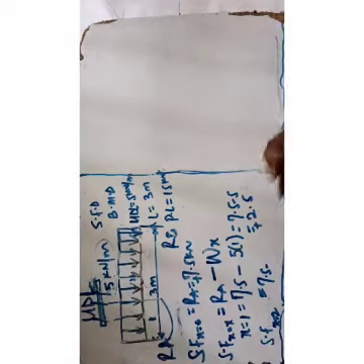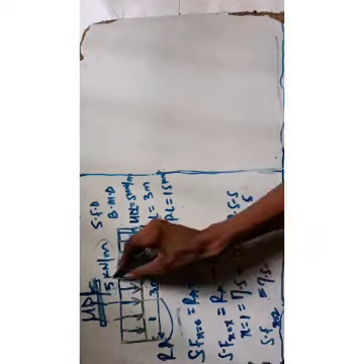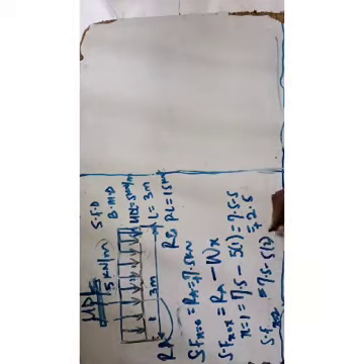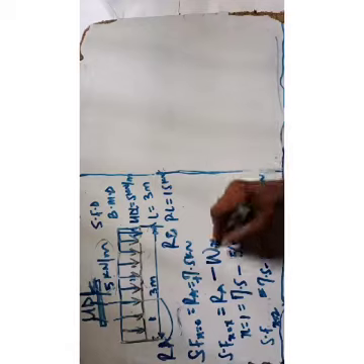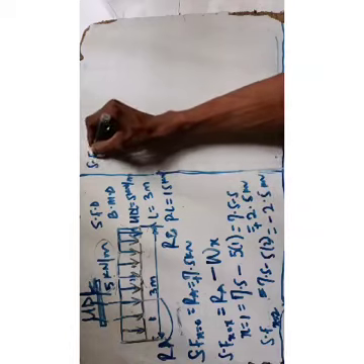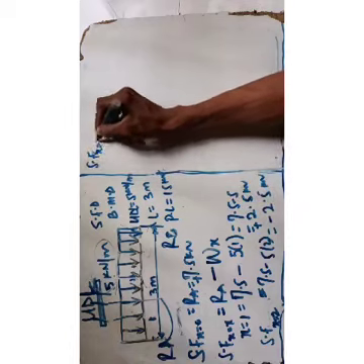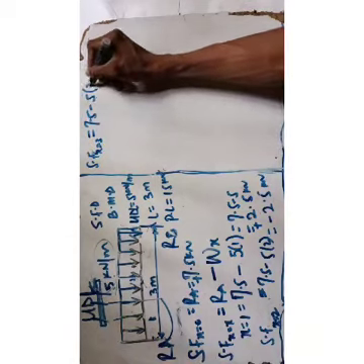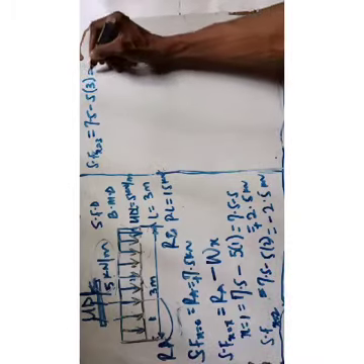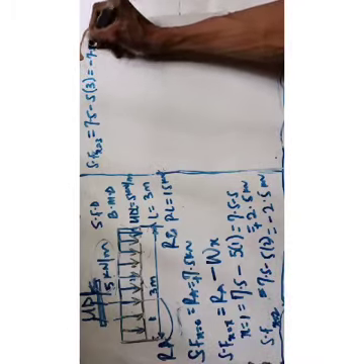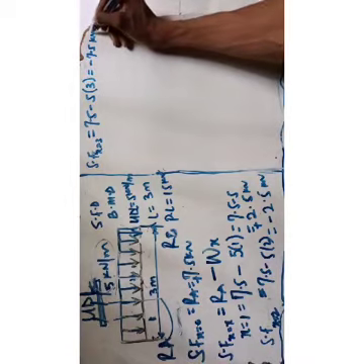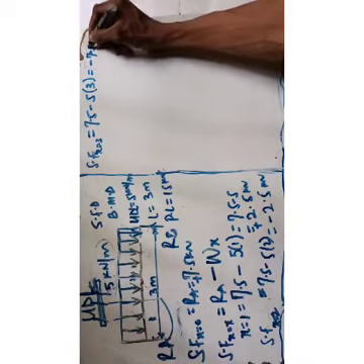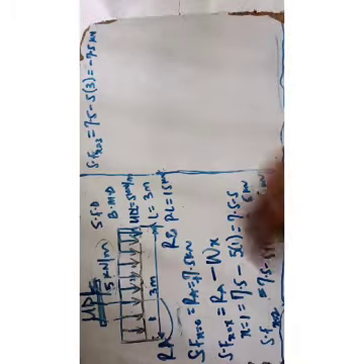So you're going to have it as 7.5 for x equals 2, 7.5 minus 5 times 2, and that will be equal to 7.5 minus 10, okay? That will be minus 2.5 kilonewton. These are all kilonewton. Then the shear force when x equal to 3, that will also be equal to 7.5 minus 5 times 3, that is the total length, and that will be 7.5 minus 15, that will be minus 7.5. This proves that UDL is always a diagonal slant. That is the shear force, okay?